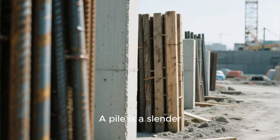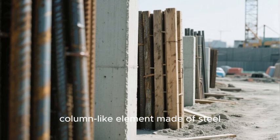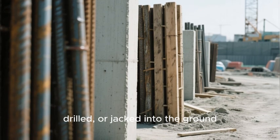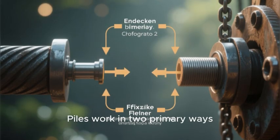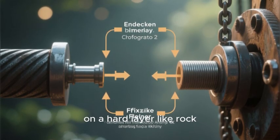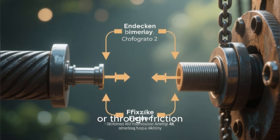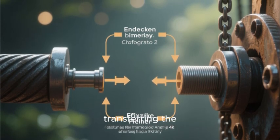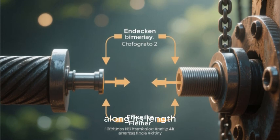A pile is a slender, column-like element made of steel, concrete, or wood that is driven, drilled, or jacked into the ground. Piles work in two primary ways: through end bearing, where the tip of the pile rests on a hard layer like rock, acting like a column, or through friction, where the surface of the pile grips the surrounding soil, transferring the load through shear stress along its length.